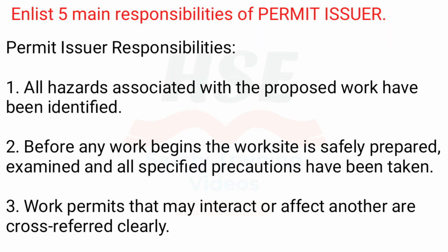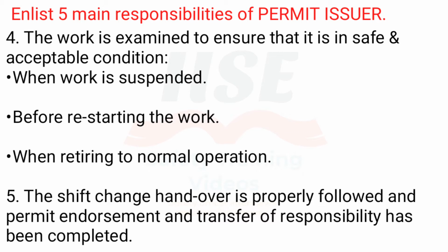Enlist 5 main responsibilities of permit issuer. Permit issuer responsibilities. 1. All hazards associated with the proposed work have been identified. 2. Before any work begins, the worksite is safely prepared, examined and all specified precautions have been taken. 3. Work permits that may interact or affect one another are cross-referred clearly. 4. The work is examined to ensure that it is in safe and acceptable condition.